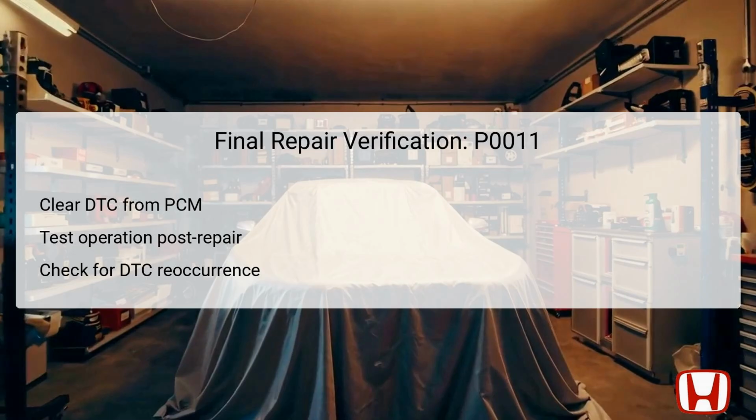Start by clearing the DTC from the Powertrain Control Module, PCM, using the diagnostic tool. Following this, a test drive is necessary to assess the vehicle's performance and confirm that the issue has indeed been resolved. Throughout this testing, continuously monitor the system for any reoccurrence of the P0011 code. Successful repairs will result in normal operation without the activation of the DTC, thus verifying that the appropriate components, such as the VTC oil control solenoid and oil passages, are functioning correctly.